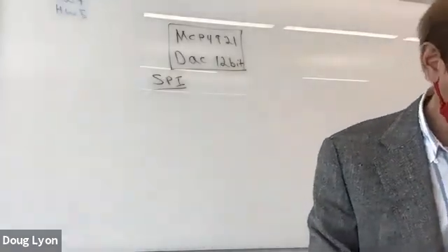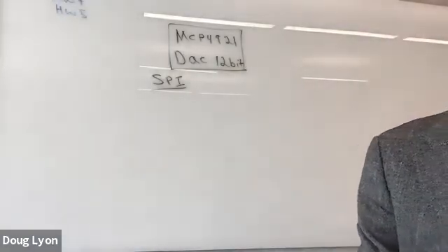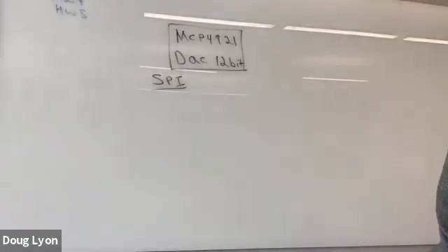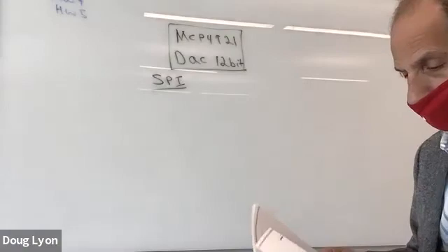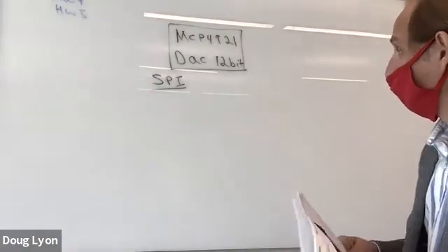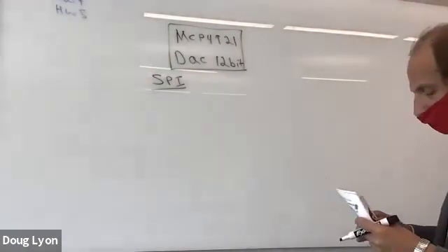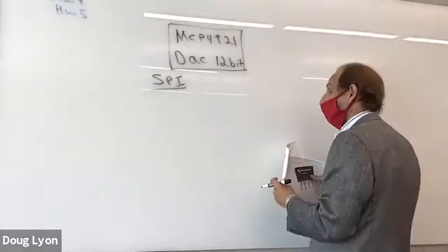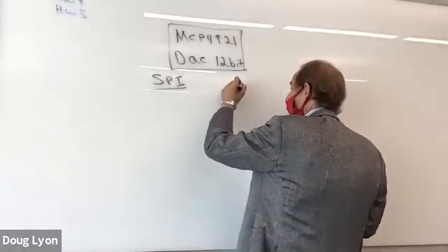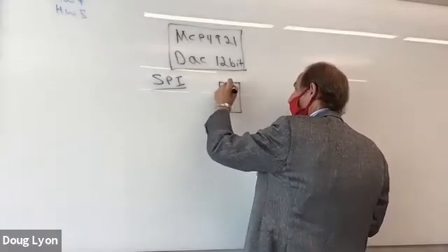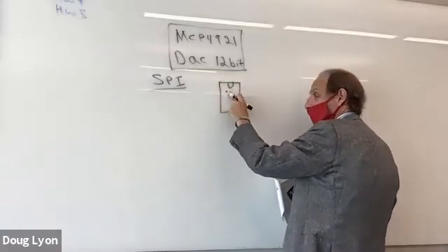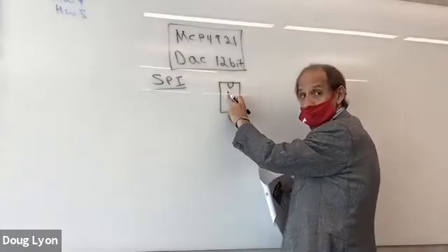And this is the reason why we've been studying it, because there are so many chips that make use of it. It's a high-performance synchronous interface. The chip itself is very convenient for us to do prototyping with because it's in an 8-pin DIP. 8-pin DIP has an orientation denoted by a mark that's an indentation on the package.